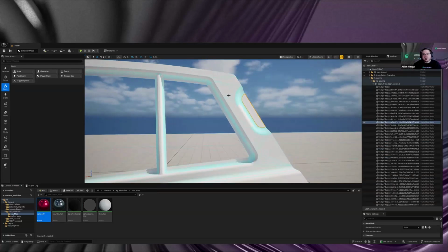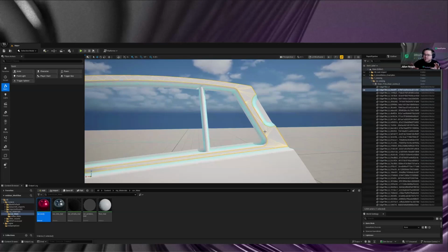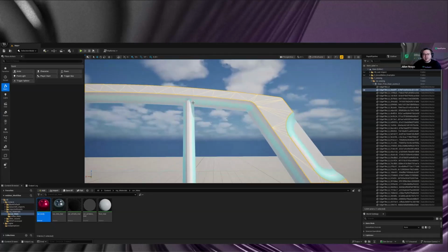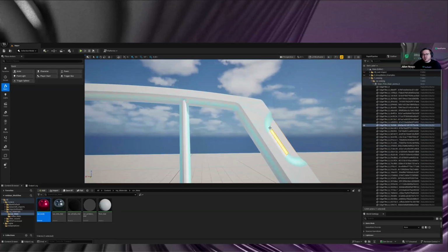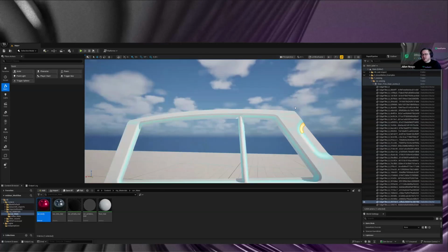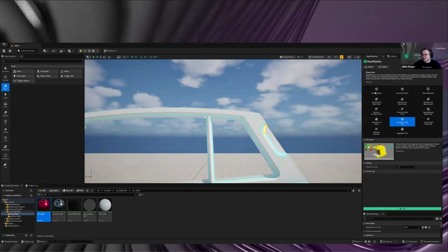And this can be somewhat annoying because ideally, you want certain separation of parts and maybe even of a larger surface in a way that actually makes sense, maybe even corresponding to the actual construction data. But in this case, we have so many little intricate patches everywhere, which really can be a problem for any process down the line. Imagine now decimating this and we end up with all these gaps and duplicated vertices where they shouldn't be, or they should actually be merged. Now, as I said before, we can select this and have a vertex merging by distance, which we actually offer. We have a cleanup mesh option where we can do that.